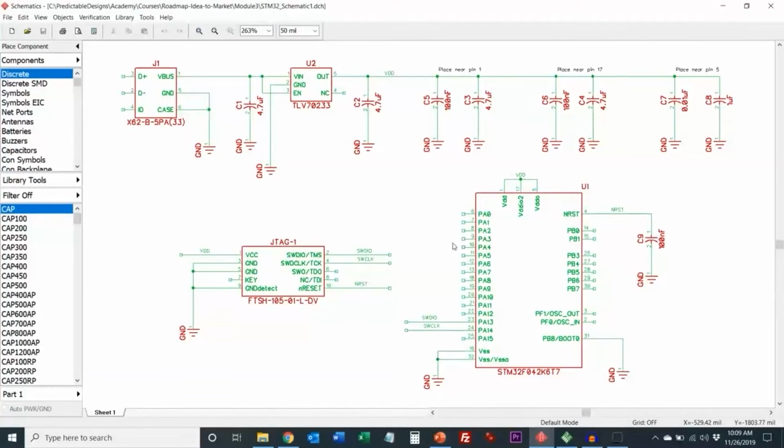A lot of times you'll see in a schematic where you won't visually see that they're connected, but the trace has the same name, and then that connects it in the software. For instance, this line here coming out of the linear regulator, I've labeled VDD. And you can see that only connects to these capacitors, but you don't see it physically connected to anything else. But what you do see is when I highlight this line, all of these also turn this blue color. This is basically showing that all of these lines are connected to VDD, even though you don't visually see that.